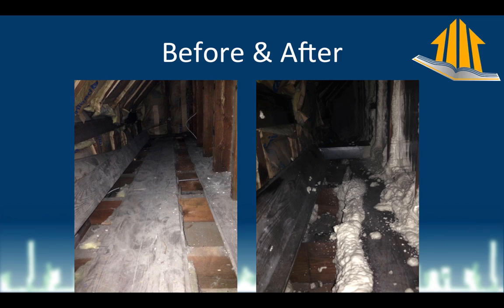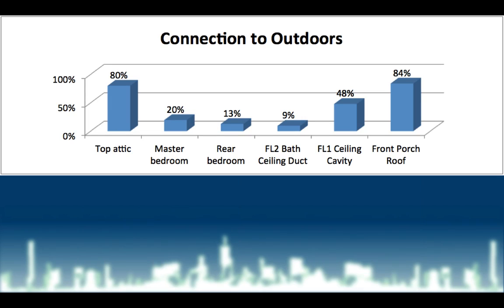So here's what it looked like before, and here's what it looked like after. Does it need to be pretty? No, it does not. It's an attic. But it does need to work. And the only way to prove that this works is by, number one, the blower door test is good, yes, but also zonal pressure testing. And again, if you are not doing this and you run a blower door test on a regular basis, you're totally wasting your time. You need to be doing zonal pressure testing.